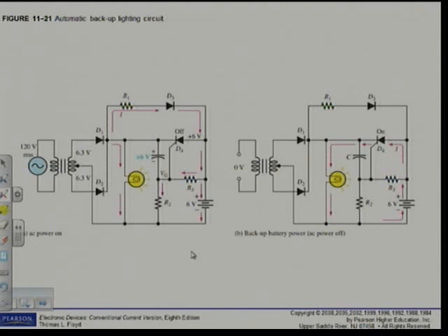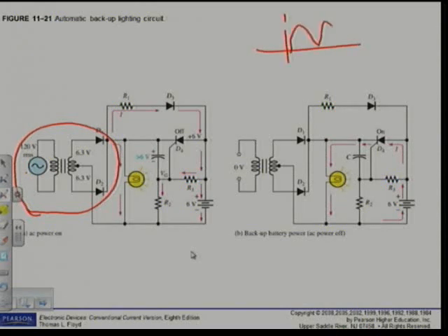If you look at this part of the circuit, we got a transformer, we got our AC supply, we got a center tap transformer, we got two diodes D1 and D2, and that will give me basically the following output. That should give me an output that's going to look like this. We will have a DC voltage. That will be 0. That will be my V peak. I will have a DC voltage from my AC supply.